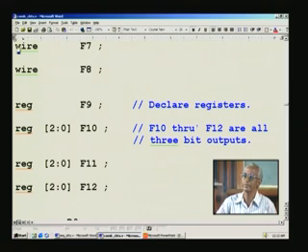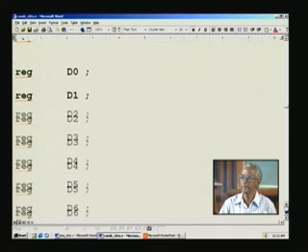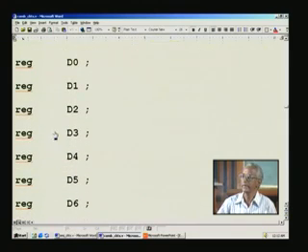So for assign statements you can say wire, and for always block whatever output, all are with reference to the outputs only, not the inputs as such. And you can refer to as a reg in always block whatever signals come in that. Once again you see here for reg multi-bit, it is through this, and for single bit we have this.